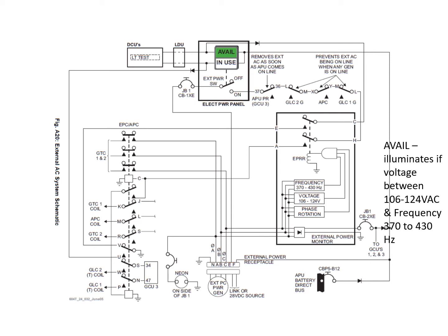And once the switch is in the on position, that allows the power coming up to go through and out of the switch to this set of external contactors, which are basically looking to make sure there's no other generator online. So no APU on, none of the two IDGs online. If that's all good, then the power can then leave that last relay.